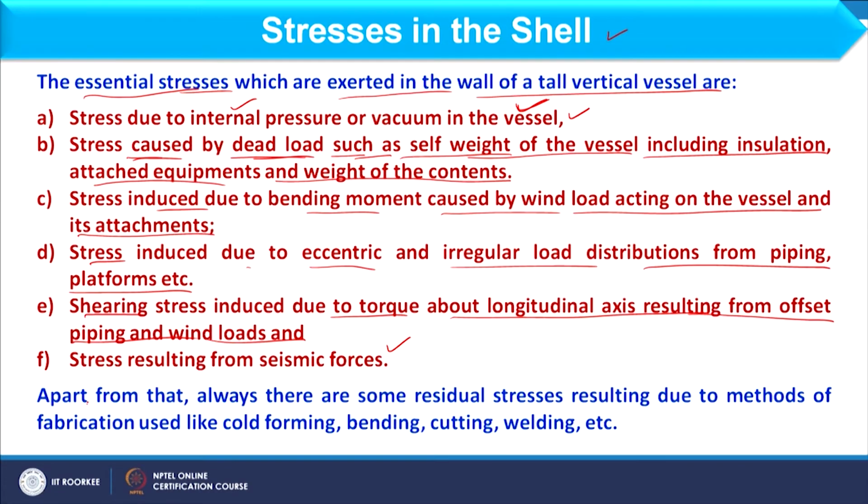Apart from that, there are some residual stresses resulting from methods of fabrication used like cold forming, bending, cutting, welding, etc. These stresses are very minimal and we can neglect them. However, the stresses which we have just discussed are prominent and should be counted.